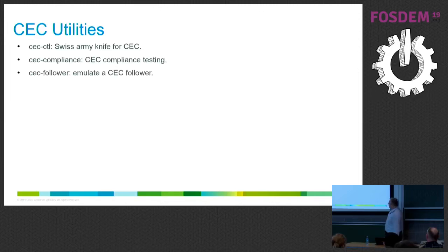cec-follower allows you to basically emulate the device that you are. So in this case, I have a laptop, I can emulate it as a playback device. So you just run it, and from the remote device, it will look like a standard playback device.